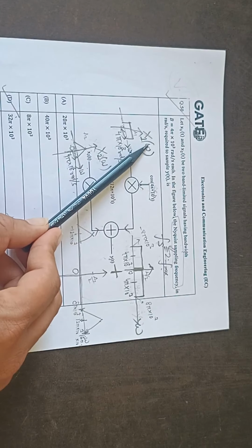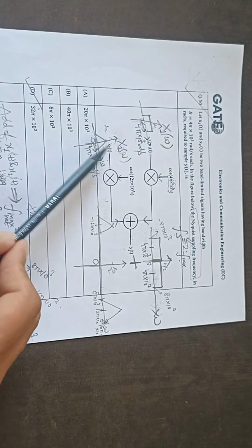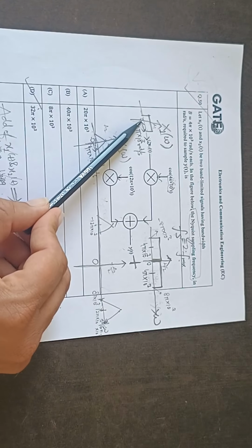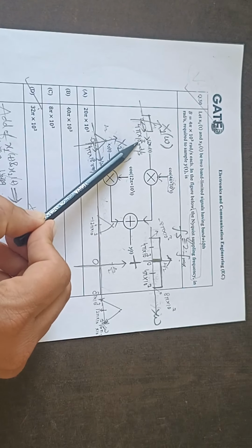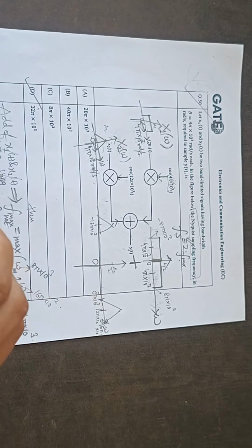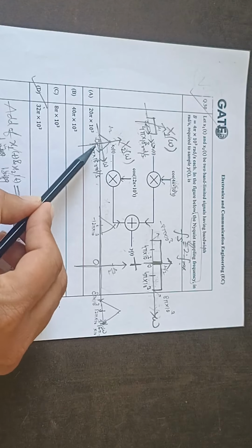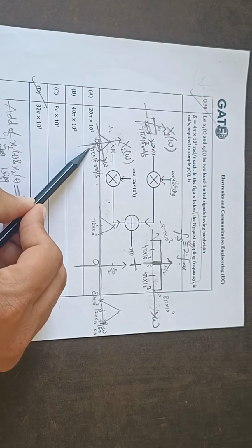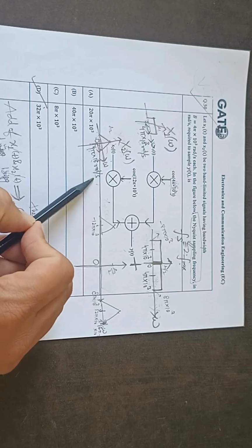So let the first signal have a spectrum like this and the second have a spectrum like this. Okay, one is rect, another tri. So the bandwidth is only for positive frequency. So this distance is 4 pi times 10 to the power 3 radian per second. This is omega, this is X1 omega, and let this amplitude be a1. Okay, and then let this amplitude be a2, and again the bandwidth is the same, both signals have the same bandwidth. So this will also be 4 pi times 10 to the power 3 radian per second.